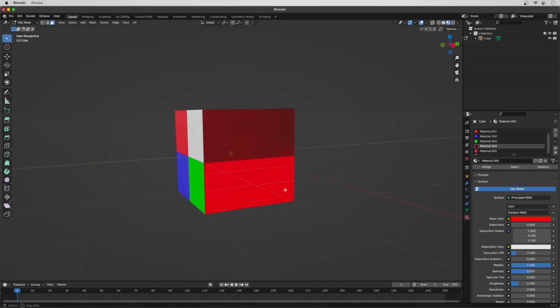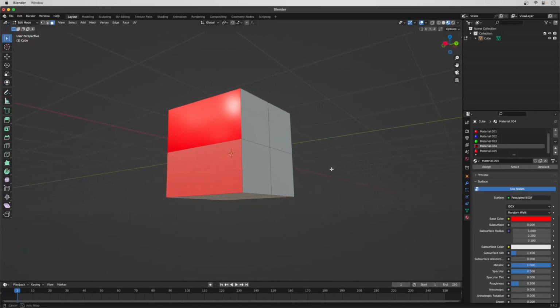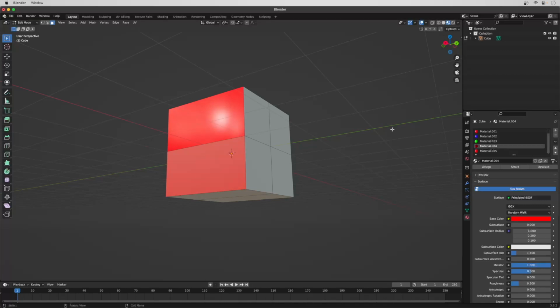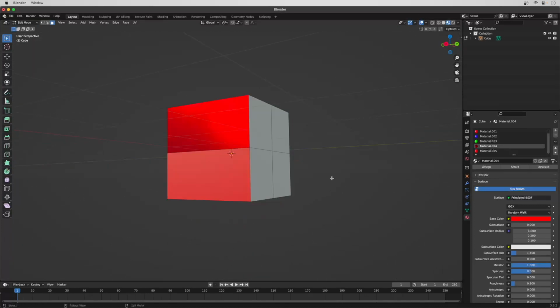Now we can see it's more shiny like metal. You can see some light here. Now if you want it more shiny, you could put the roughness to say 0.1. Now that really looks like a metal. Now you know how to paint something if you want it to look like metal. So now I'm going to move on to the next side to make a mirror.